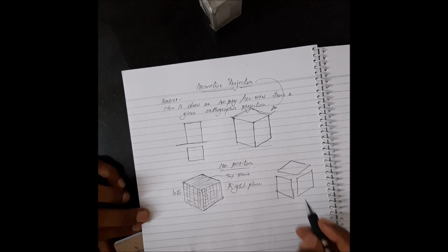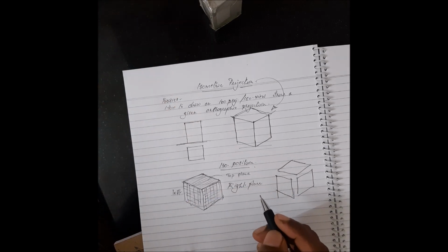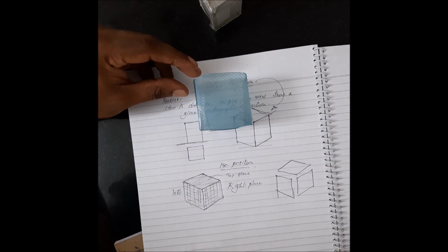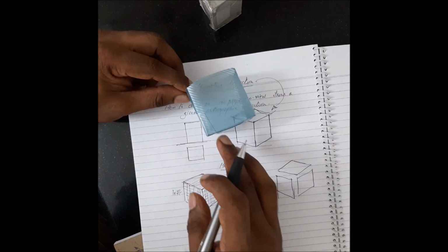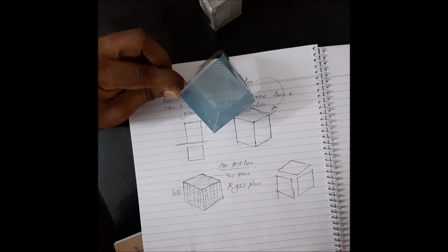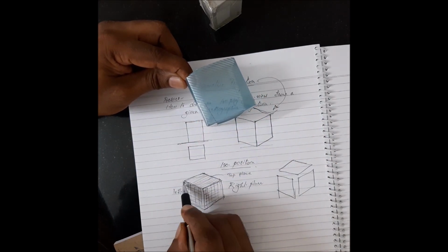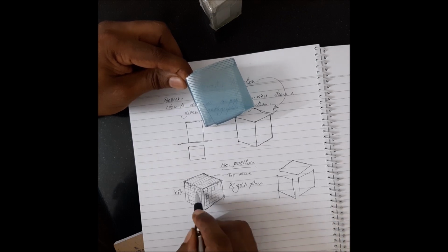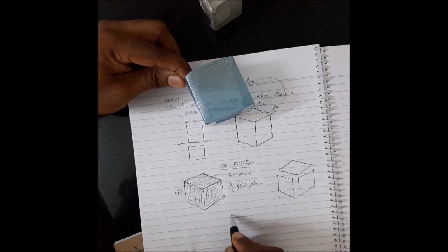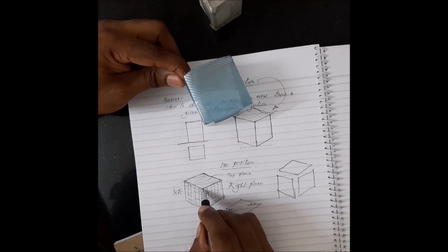Have you noticed something very special here? Initially the cube was at rest. Let's say this cube is right here. So the top plane of the cube is right here, the right plane is here, left plane is here. When you rotate the cube and place it in the isometric position, the top plane has 4 horizontal edges. All these 4 horizontal edges will be inclined at 30 degrees, which means this is 30 degrees, this is 30 degrees, and these are also 30 degrees. And all the vertical edges